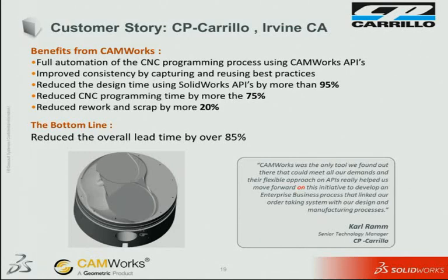We have a stock manager, and you can create stock from an STL file or from an extruded sketch in SolidWorks. You can also just automatically get a bounding box around the part, and in an assembly, you can also create stock from a SolidWorks part as well.